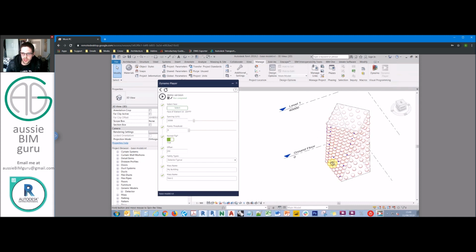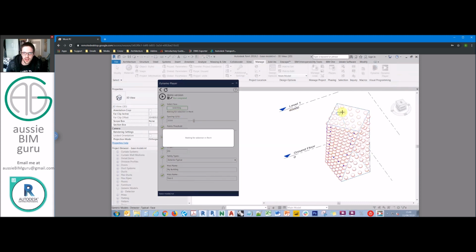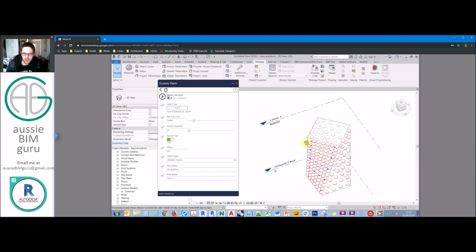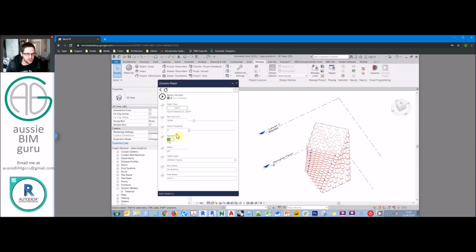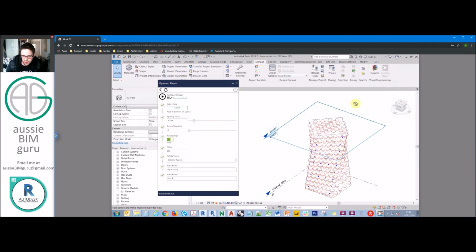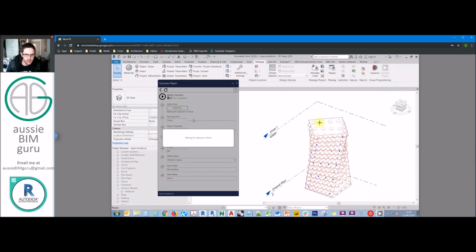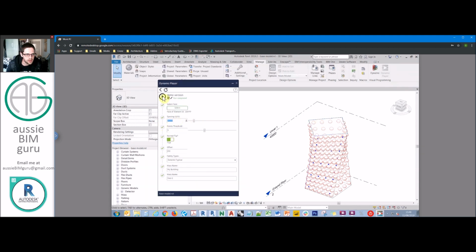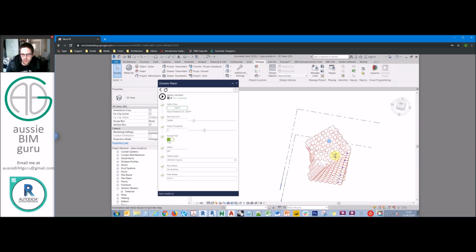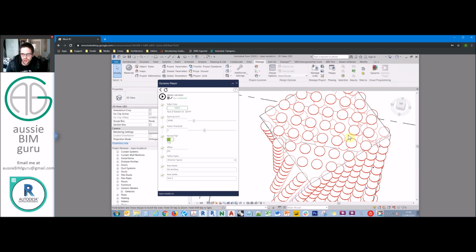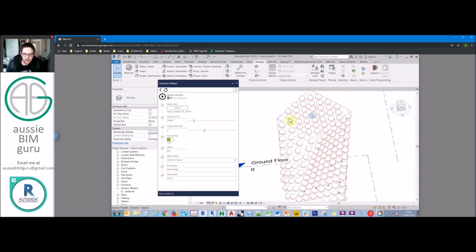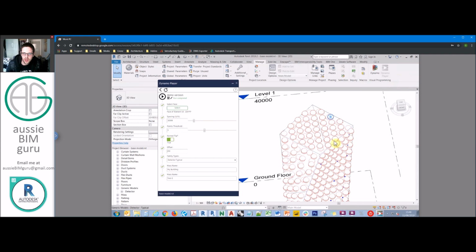So I was saying before with the top surface that it won't deal with it as easily because its normal is at a different direction to its ISO line. So if I ran it on just a point threshold of 0, we might not get enough points. In that case we sort of did, but if I put my threshold up to 1 for example, and I try again with this spacing, we may get slightly more points. So see how it fills out the face a little bit more, but you will get some peripheral points that are almost outside. So basically what's happening here is as long as there's at least 3 points of the panel intersecting with the test surface, it will allow it through.